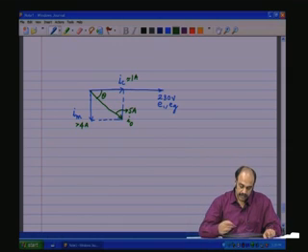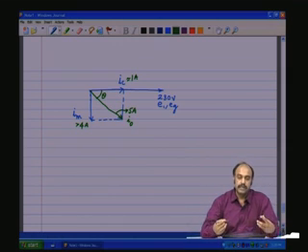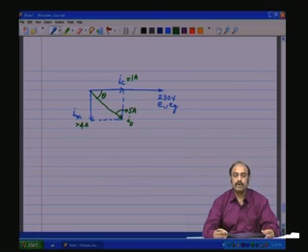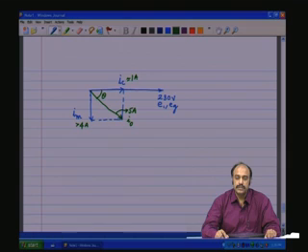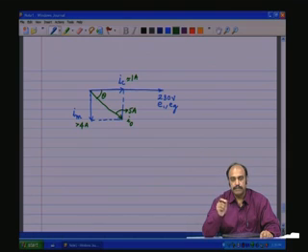So, what we have done here is introduced two non-idealities, the loss component and the finite permeability component. Now, we also have to see that whatever ampere turns the primary current is generating, which is N1 into I1, is going to have a motive force within the core of the transformer.